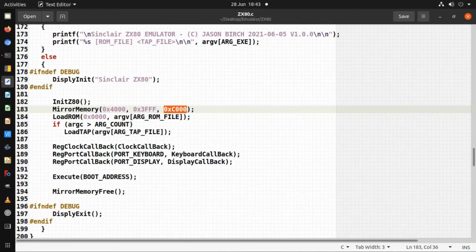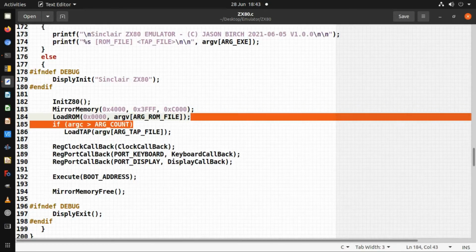So effectively it's up to about 64K of RAM, but because this memory, which is 16K, is mirrored, you only really get 16K of usable memory, which I guess was the maximum you could plug onto the actual system. I do remember on ZX81s there was a Memotech memory expansion, for sure. I'm sure they were 32K or something. I guess they must have been switching pages of memory or something. I'm not quite sure how you got a 32K RAM pack on the ZX81.